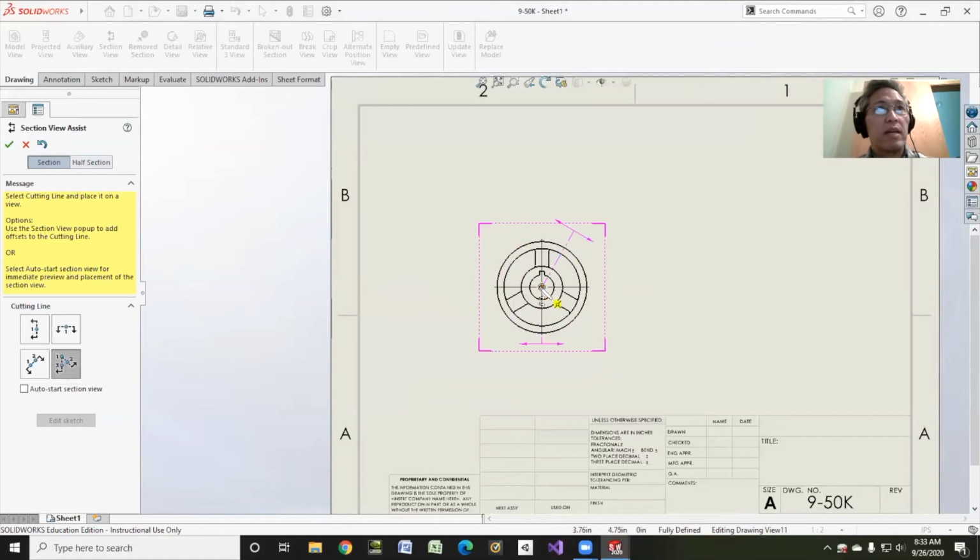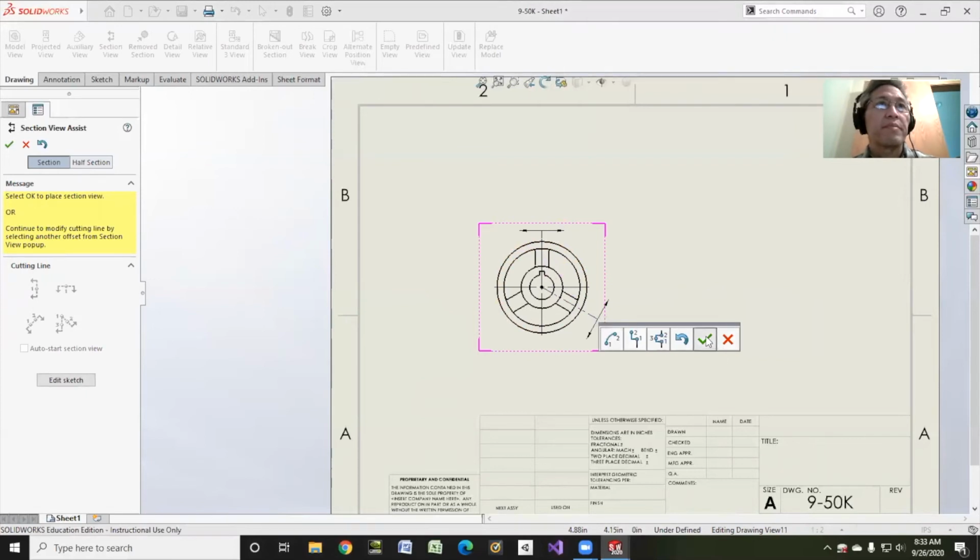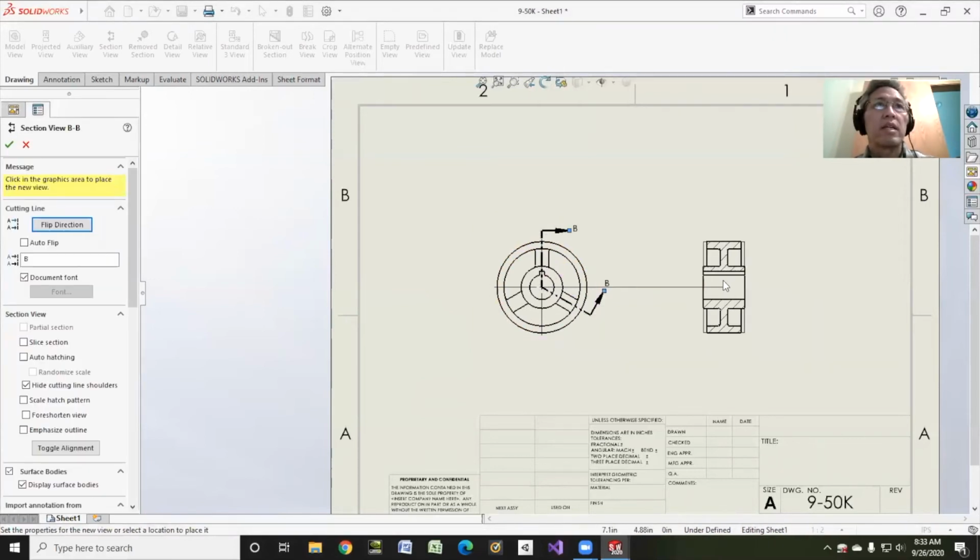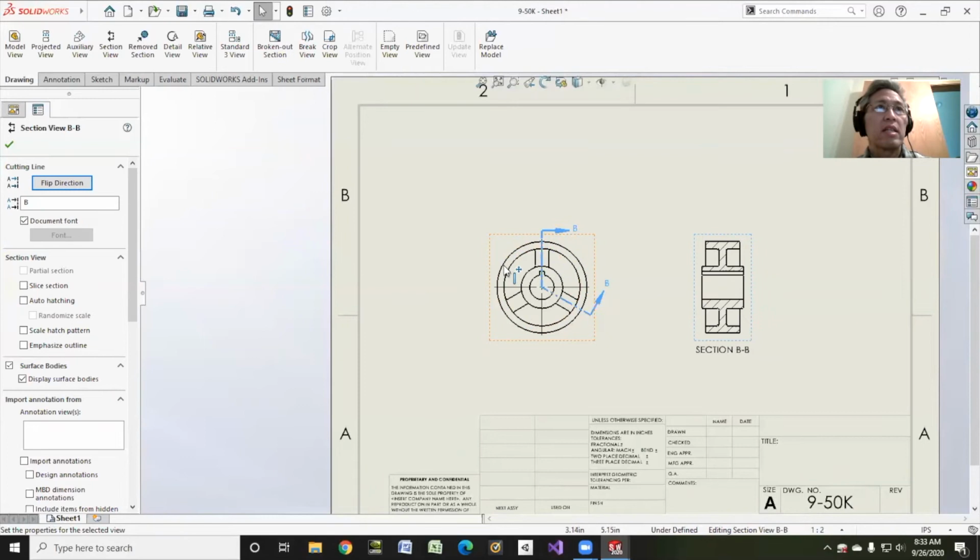Now I'll grab the center. Then I'm going to grab vertical. Make sure that little yellow vertical is there. See how it's not there, and then it is on the right side of that pencil. So make sure it's vertical. Now, really nice if we could just make this parallel with this guy, but we really can't. We just kind of eyeball that to make it parallel to these 2 lines here. So I'm going to just eyeball that, and that looks good. Click there. I'll hit the check, and I'll place this guy over here. Now, the arrows show that it's actually looking from left to right.